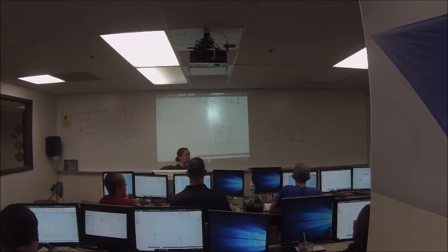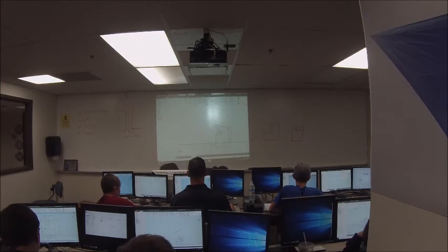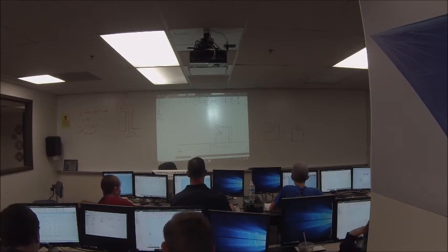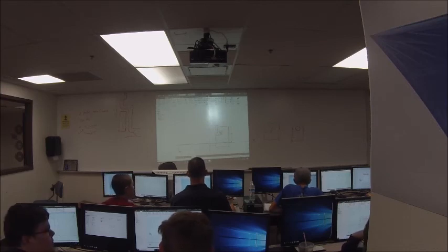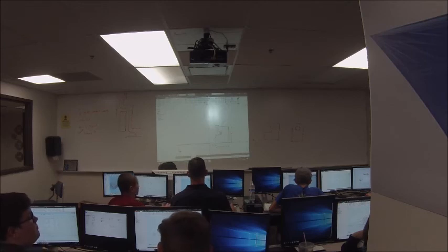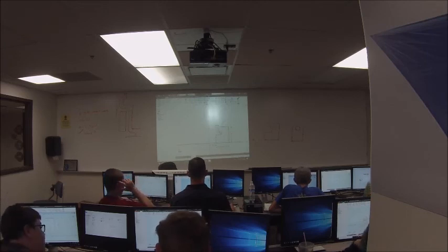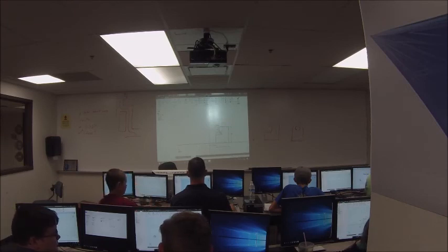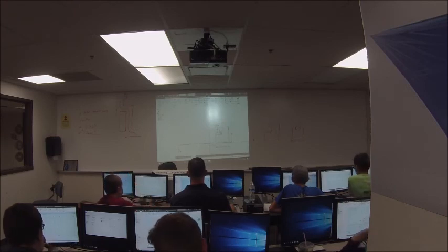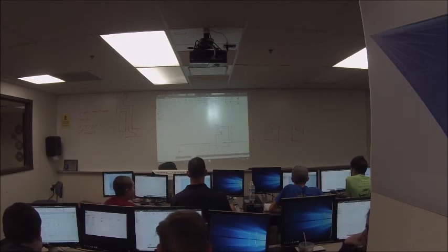You'll have to put horizontal constraints. It says I need dimension. What does this button do? Configuration issues detected. This doesn't have a position in the space. So you can do a horizontal constraint between this corner and that, and line it up. I think I messed it up. And you need dimensions as well. If you look at my screen, try it, and dimensions.